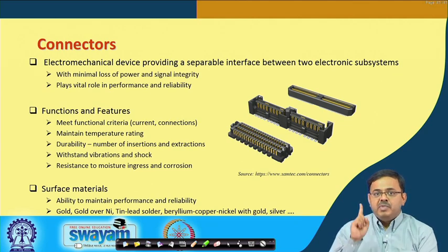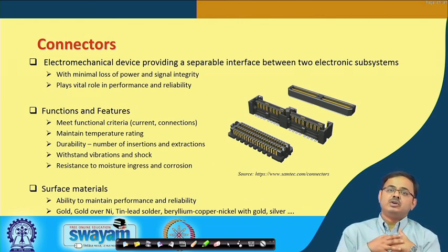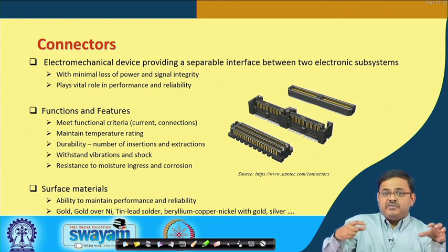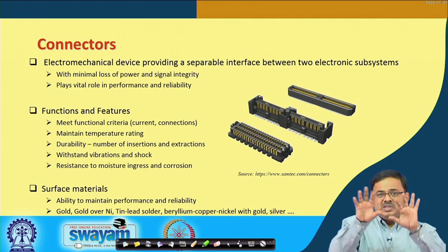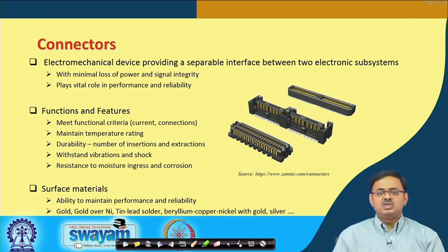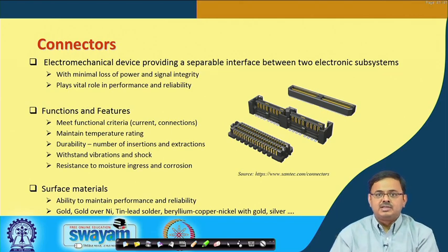So, with minimal loss of power and signal integrity, very important. The electrical connection has to be very good. It cannot be a tarnished surface, there is a loss of signal and all that stuff. Many a times we see if we do not connect our projector to the CPU tower in our desktop, you will see that the display on the projector is not great. And then sometimes say, okay, tighten the connector. And then when you tighten it, suddenly now you see the better colors, right.